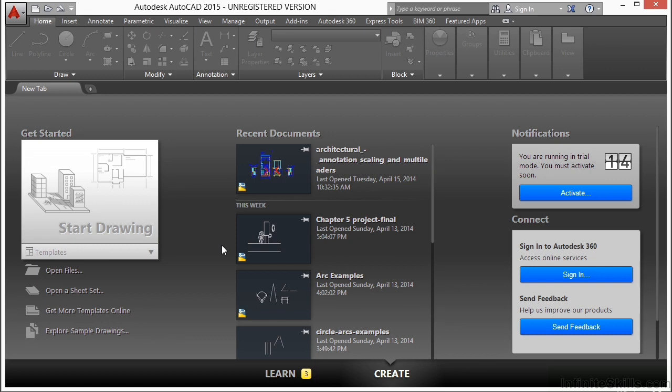A good CAD tip that I can give you is to keep your work area neat and tidy. That's the idea about this next video that we're going to look at here. We're going to use the Delete Duplicates command. The Delete Duplicates command is also known as the Overkill command. Originally it comes from an add-on tool pack called the Express Tools that used to be a big extra feature you had to pay for in AutoCAD. But now a lot of those are just built into regular AutoCAD. Now Overkill will delete duplicate objects, merge polylines, and get rid of messy line work.